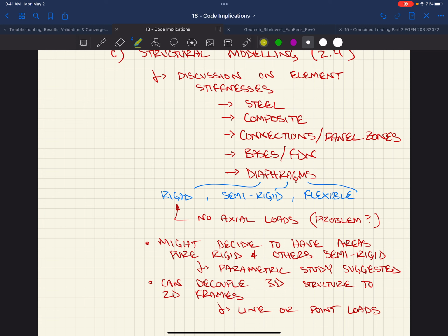Okay, it's the lower bound stiffness associated with having the shear flow attachment of your stud. Each one of these had a Q. It was your shear flow, like how much stud strength you have per stud. And that allows you to transfer the shear flow, which then allows you to have an axial force in this, which gives you moment. Shear flow gives you moment. Shear flow comes from a change in moment. And so this I lower bound, which there's tables in the 360 manual. And so they say, okay, you can come up with an effective EI.